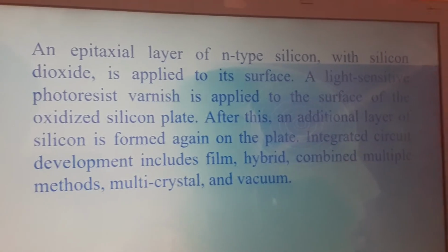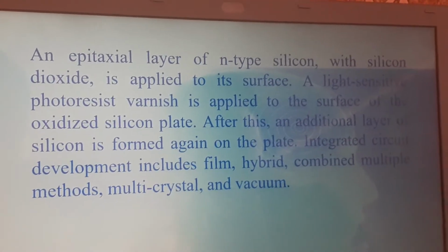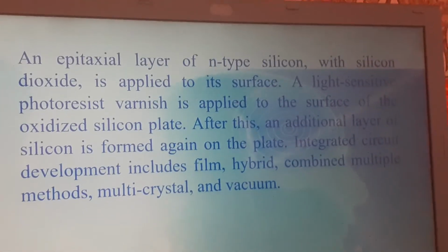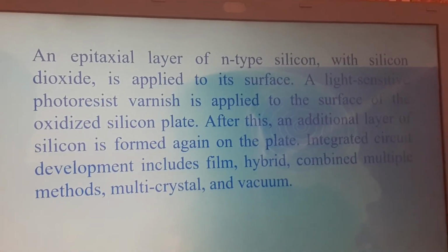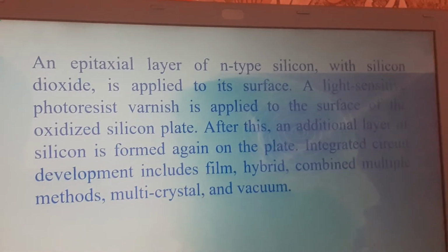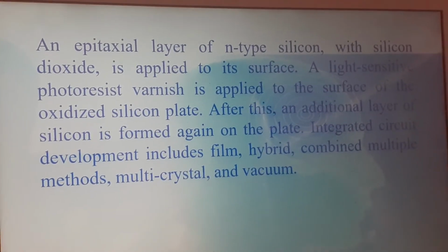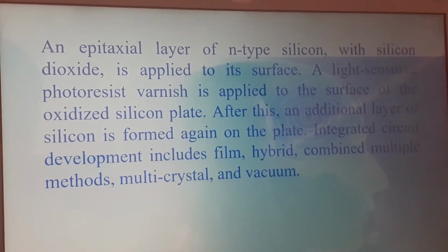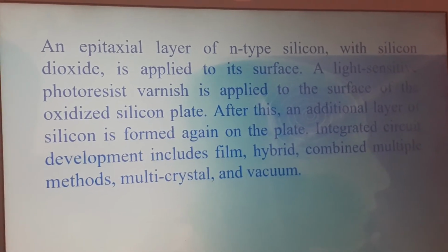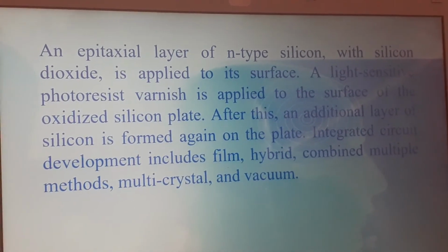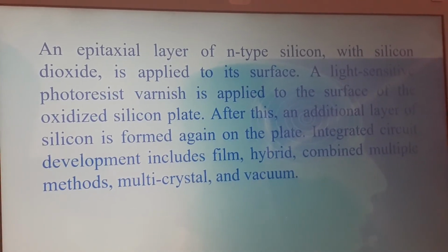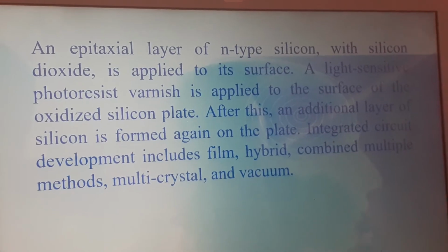An epitaxial layer of n-type silicon with silicon dioxide is applied to its surface. A light-sensitive photoresist varnish is applied to the surface of the oxidized silicon plate.